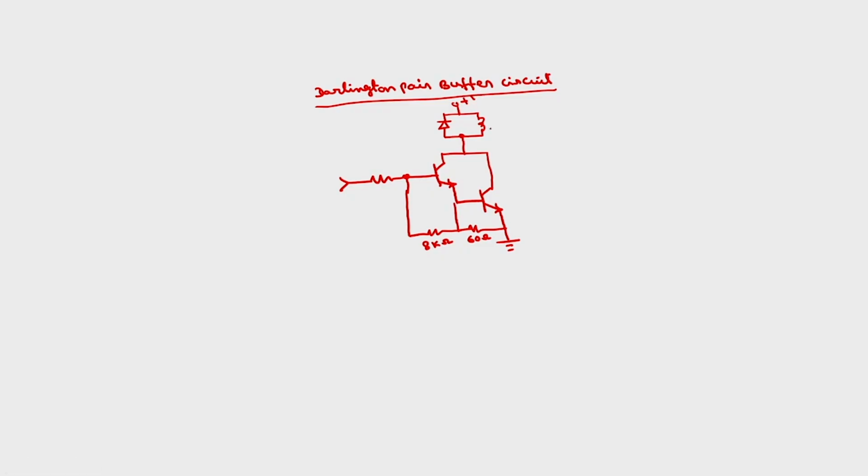This can be either a solenoid or coil, relay or solenoid. Depending upon the voltage required for the relay, we will choose this V. That is why I have written this as V. This may not be 5 volts, you can actually take a higher value also. This you have to take from the output port of 8255.